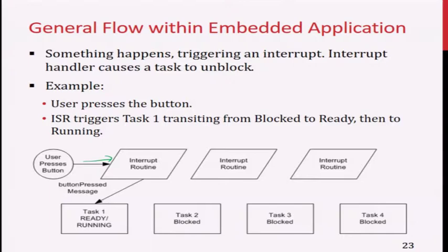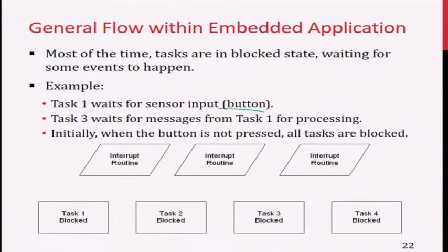So this interrupt service routine must send a message to this task to go and take a picture. Before that, you will see that the task is blocked. You do not want your camera to be continuously taking pictures throughout the day, correct? But your camera functionality must be there on standby mode. It's in a blocked state, waiting for the event that somebody presses this camera button.